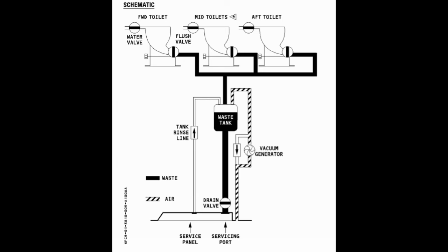The lavatory flush valve or drainage valve can be manually closed or opened if there is a failure of the electric motor to drive it closed or open. The waste tank or tanks generally will be found in the rear fuselage area of the aircraft, either at the back of the rear freight bay in the sidewalls or in the void behind the rear freight bay.